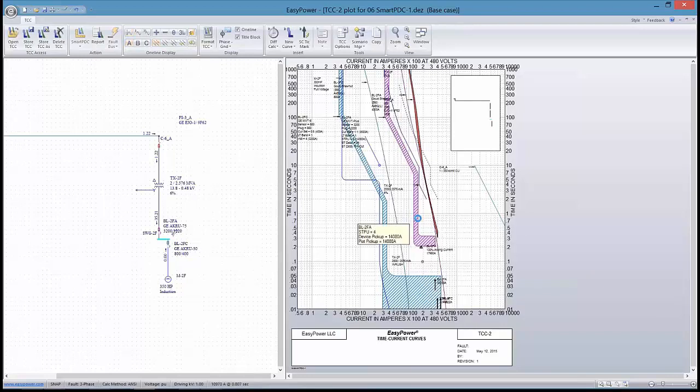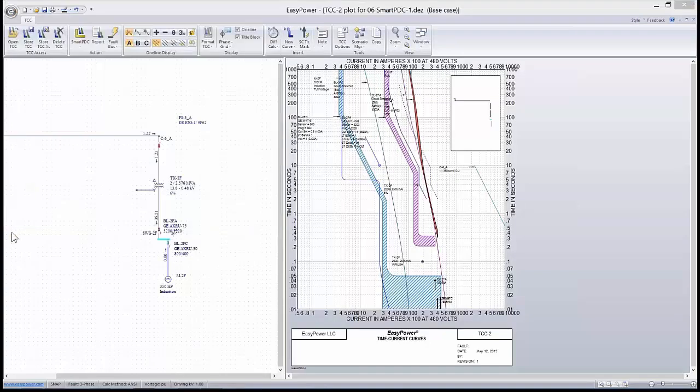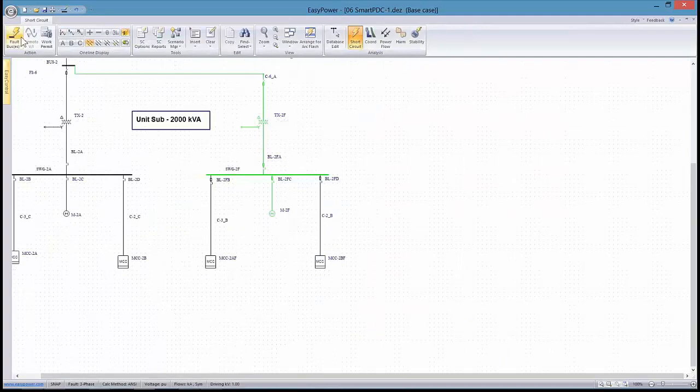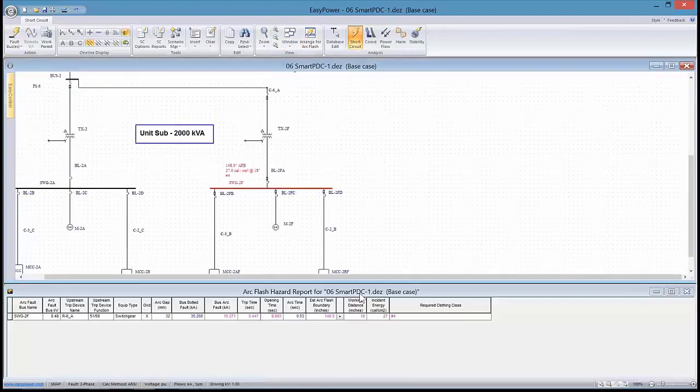As I adjust this curve such that I know the 85% point now is what's taken effect, I can go back and look at my arc flash incident energy calculations, short circuit, fault this bus, look at incident energy. Now you can see the type is magenta, and that's because we're calculating 85% of the maximum fault current, which gives us a slower opening time.